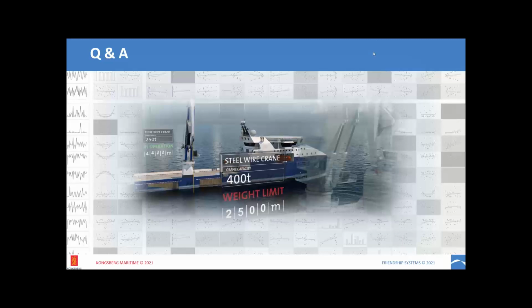Yeah, thanks also for the question. Definitely, yes. One way could just be to make these variables actual design variables. So when I said that prismatic coefficient or longitudinal center of buoyancy would be fixed, I could just as well make them a design variable and change them throughout my study. But I could also just skip the Lackenby transformation in the very end and say I'm happy with whatever I get after all of my transformations.